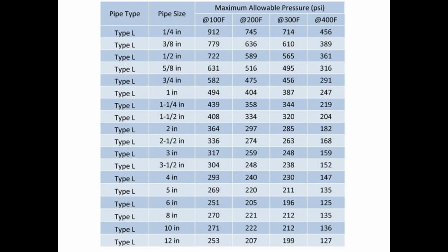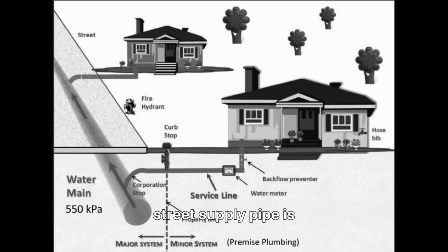If you're applying a simple 5 psi per 100 foot limit without worrying about velocity, you can use the simplified tables, figure 3.7 for copper or figure 3.8 for rough pipe, to quickly find the correct pipe diameter based on fixture unit range. The sizing of the street supply pipe is a special case. It's handled differently from interior distribution piping.